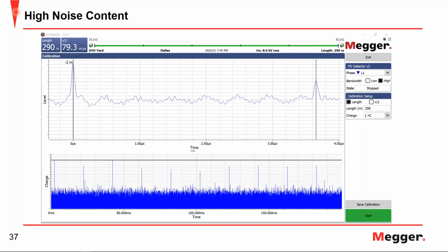Now, in this instance, what I did is I took the grounds and I looped them, as I said I shouldn't previously. So I went against one of my best practices. And what I also did is I moved and poorly connected the calibrator leads. You can see that with the exact same settings of 1 nanocoulomb, still on phase 1, we were getting a poor signal to noise ratio with erratic charge signals being injected, and our TDR pulse is nothing, right? Could not be usable.